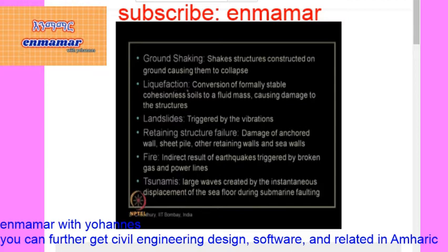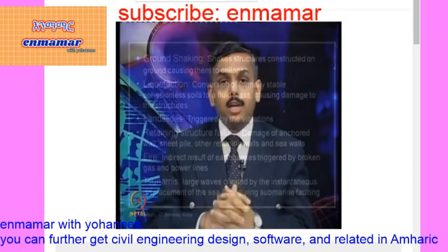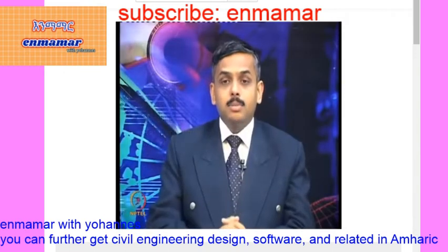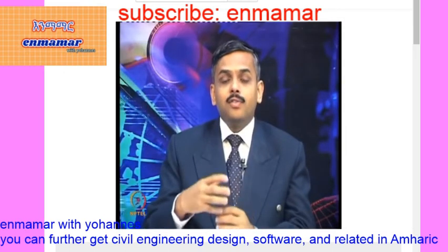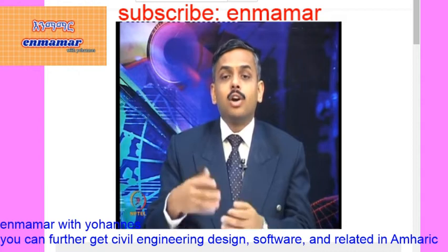What is liquefaction? In common man's terminology, it is nothing but the conversion of a formerly stable cohesionless soil to a fluid mass, so it causes damage to the structures. As I have mentioned in this sentence, a cohesionless soil, typically below the water table, will start flowing as if it is a fluid or liquid.